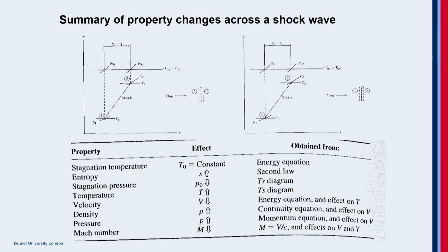Okay. Now before we go into the stability of shocks, we need to get this understanding right. This is the pressure at 1, P1. This is the shock. Let's say this is a strong shock. When there is a strong shock, it jumps to pressure P2. The temperature increases, and here is the total pressure.